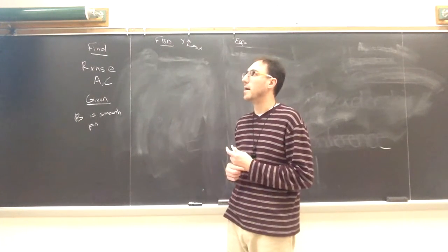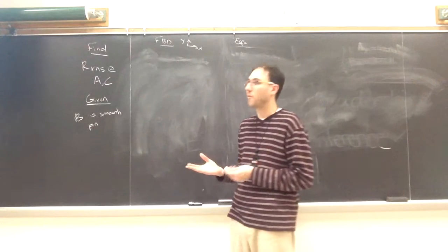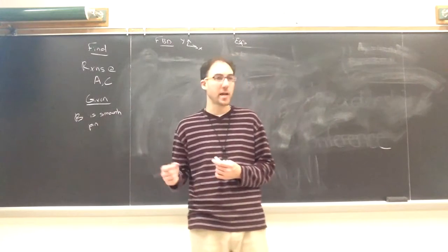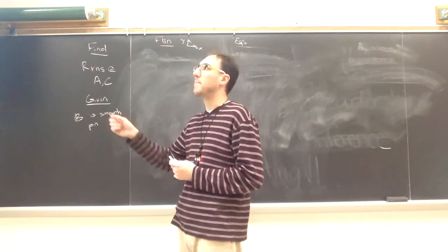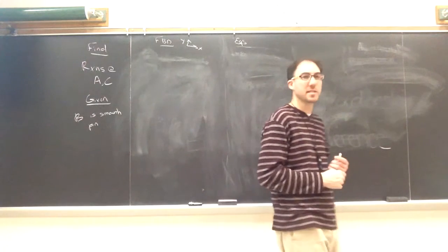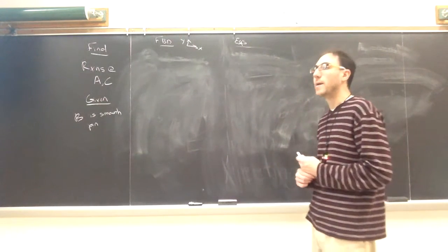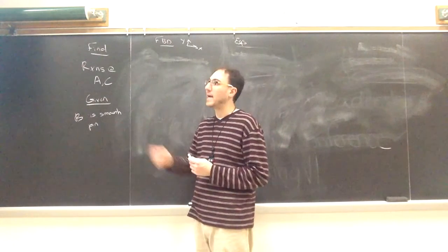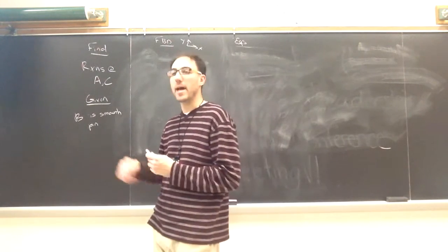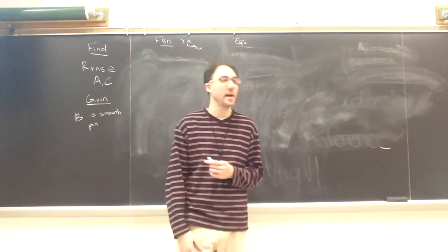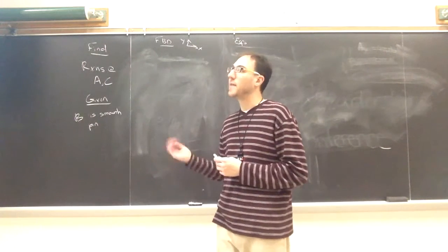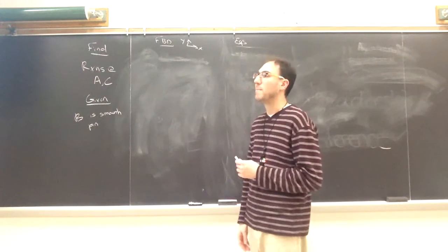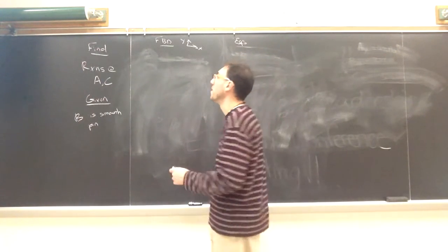BC, first of all, it's fixed at C, so right away we can't identify it as a 2 force member because it's not 2 pin connections. And AB is pinned at A, but it's not pinned at B. It has a peg and slot, which is going to behave differently. So AB we cannot identify as a 2 force member either. BC also has a force along its length, so that doubly disqualifies it from being identified as a 2 force member. So we can't use any of that information to our advantage, but we can separate it out into its individual members and start to solve for some of our unknowns.